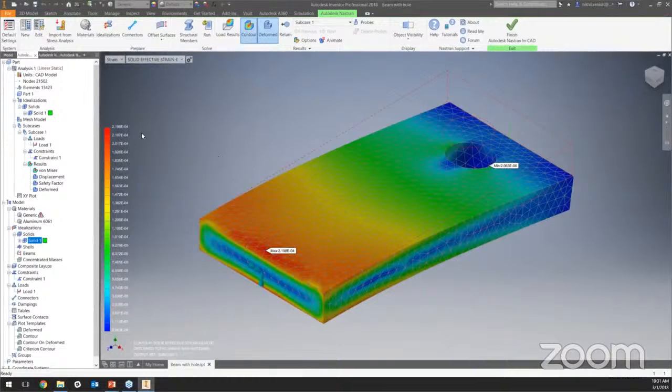I know that when I first started doing simulation, almost 6 or 7 years ago, I was just like, man, I've got a really awesome computer. Let me just make the mesh size infinitesimally small and run this thing for like 16 hours. And then you get an answer that's maybe like 0.5% better than the one that took you 30 minutes. It's not worth it. Yeah. So definitely something to keep note of: where to stop refining your mesh. At what point you hit that barrier, you've hit that convergence. Yeah. So definitely keep that in mind.